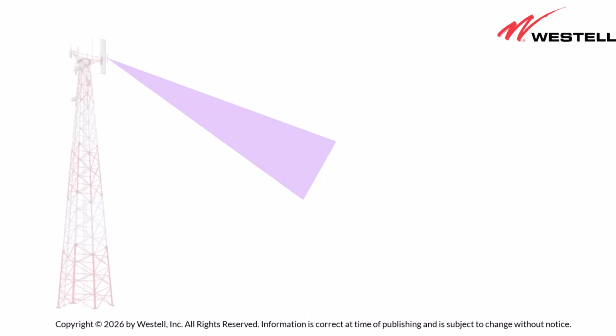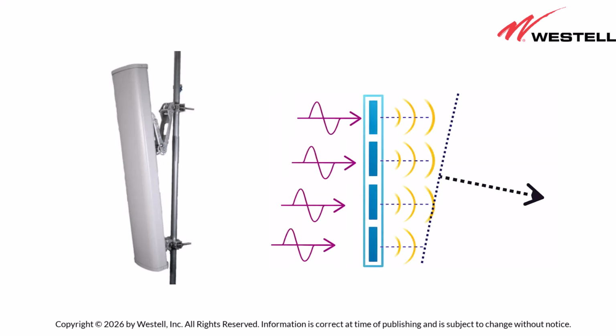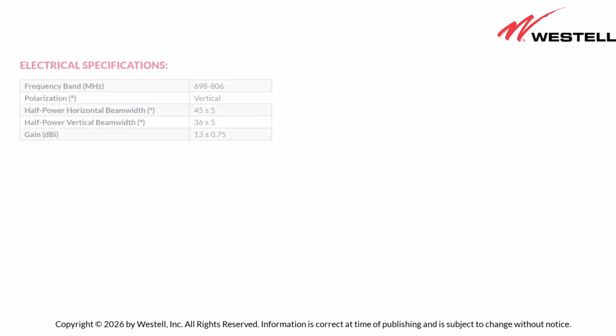It can be accomplished through mechanically tilting the antenna or electronically by manipulating the signal each of the stacked dipoles receive. Indoor antennas are usually very low gain, so they direct a lot of energy towards the floor without the need for down tilt. There are a few other specifications to consider about antennas.